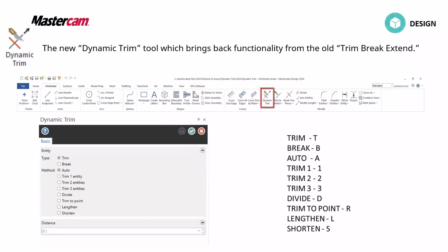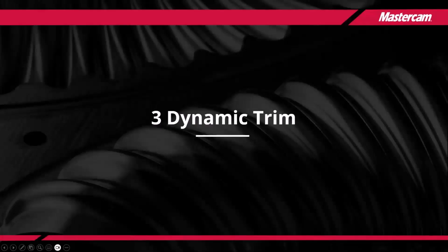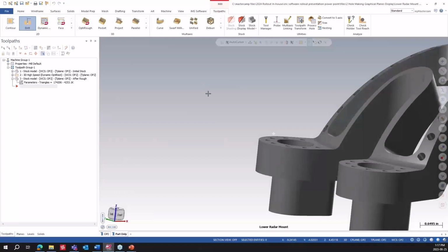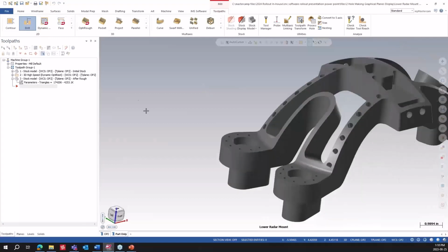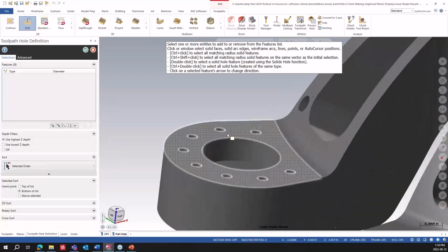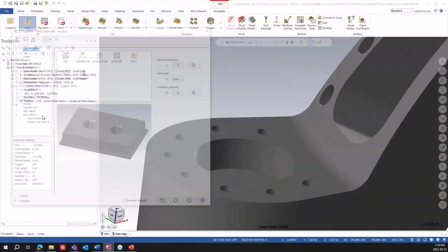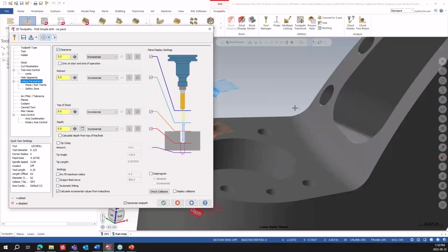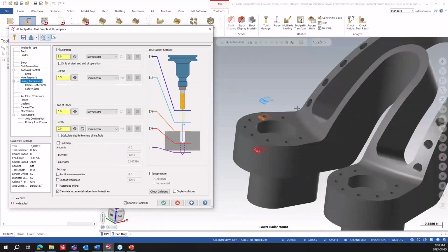Sorry to interrupt, there's one quick question here. It says, is using the drill height plane tool per instance or for all holes in the op? No, that would be all holes in that operation. It's as you selected, because you had selected all of those holes. You could apply it to one hole itself if you wanted to grab just the one hole, and you'll get the linking. So if there was one that was deeper or lower, you could do it that way, and like I say, you can grab those on the screen and drag them. I think that answers that question.